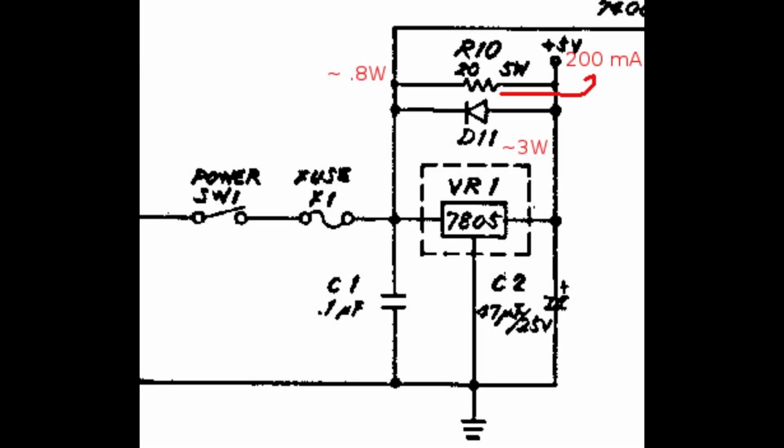The second modification is relative to the 5 volt power supply regulator. The original Commodore solution was to use a normal 1 ampere linear regulator, the ubiquitous LM7805, but since the current needed was too close to 1 ampere and also the power dissipated to drop the voltage from 9 volt input to the 5 volt output was too high, even when using a heatsink, they had to add a big power resistor to divert some current away from the regulator and bring it directly to the 5 volt line.